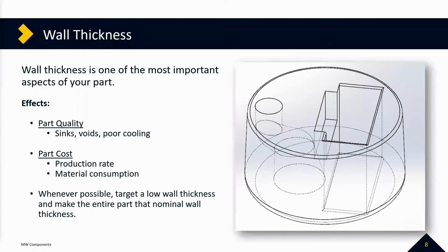Or worse, there's kind of an invisible defect called voids, where the skin might flash freeze more or less, and then the material will shrink towards the outside of the part and leave just pockets of nothing within your part that you can only really see if you cut it open or if you have clear parts.